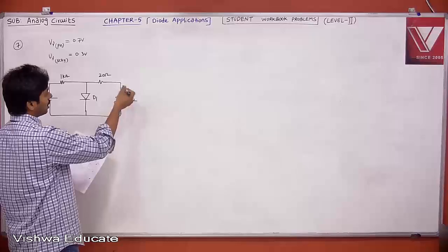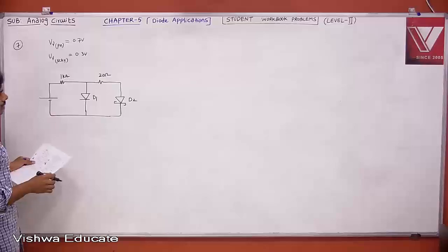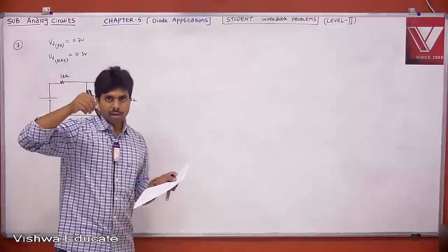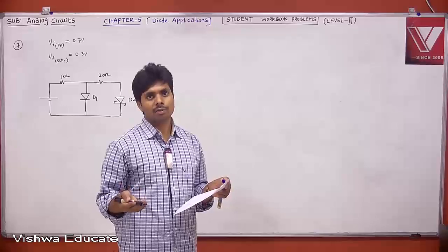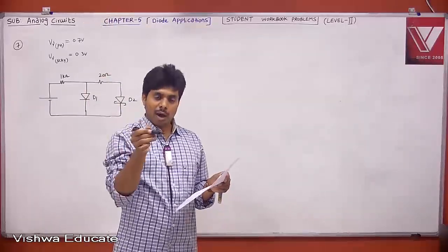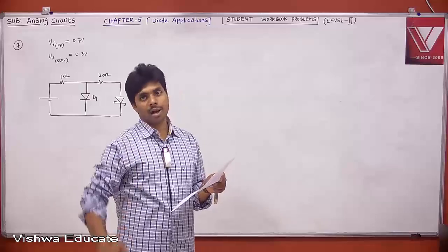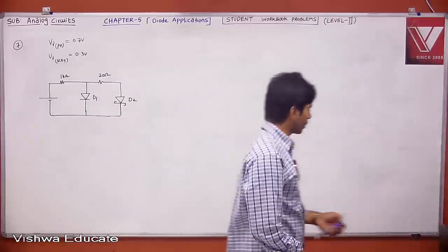The Schottky diode, a metal-semiconductor diode, has a lesser V gamma. You get that when a metal wire connects to a semiconductor in fabrication. For a MOSFET, the drain and source are connected to external wires, and then that wire and the semiconductor will have a Schottky diode action. That is having V gamma 0.3.